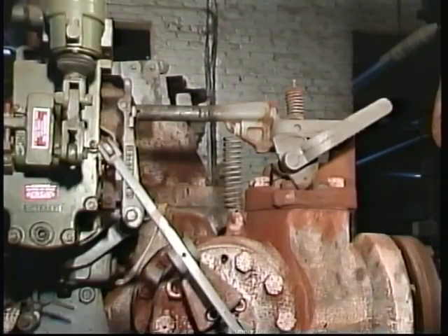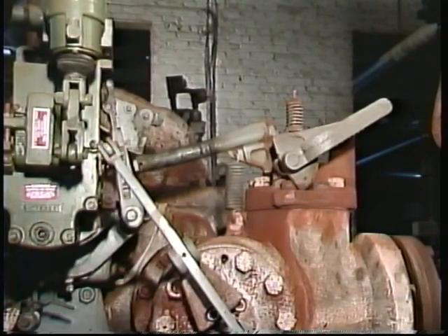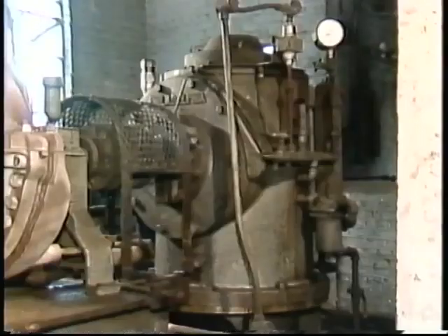If the pump's oil level drops below a certain point, a solenoid trip is activated to stop the turbine. This prevents the pump from being severely damaged by continuing to operate without proper lubrication. By now, you should have a good general understanding of the basic components and functions of a typical non-condensing steam turbine and its auxiliary systems.